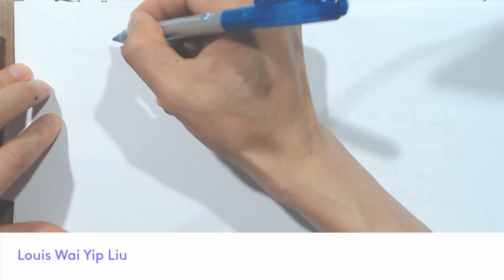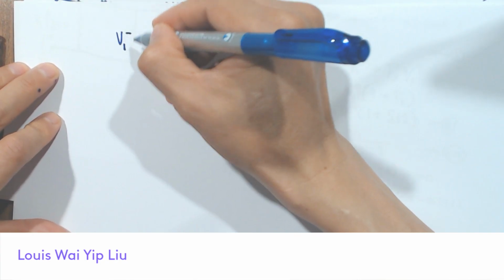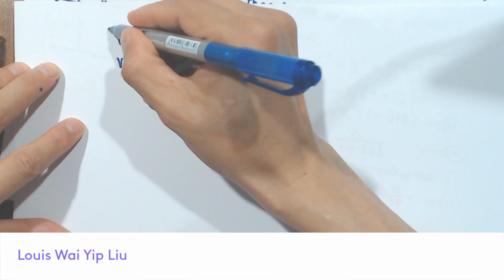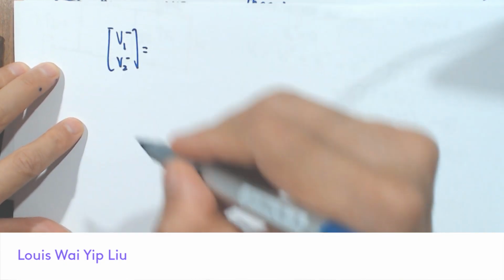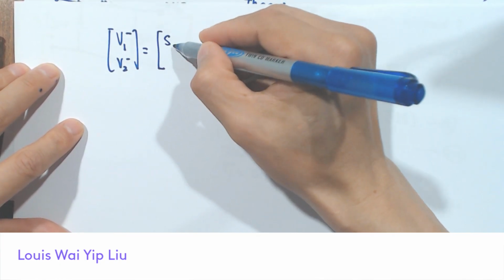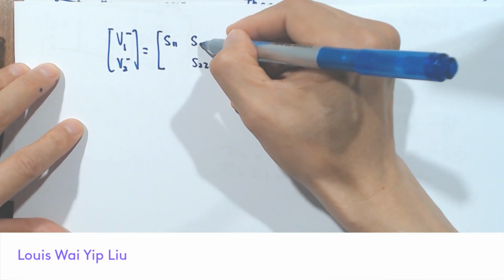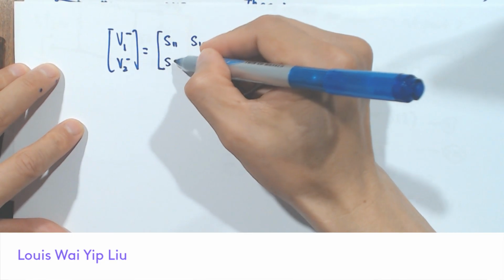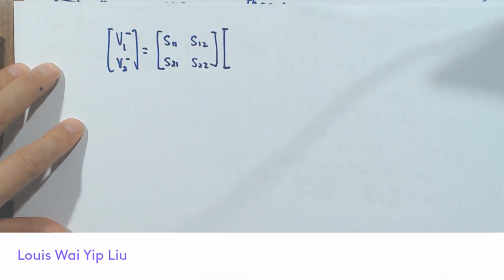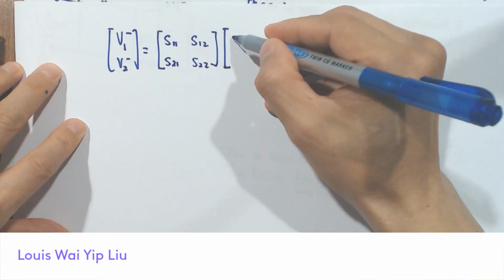So V1 minus, V2 minus, according to our understanding, is equal to the matrix S11, S12, S21, S22 times V1 plus, V2 plus. So this is the way we develop the system equation for S parameters.